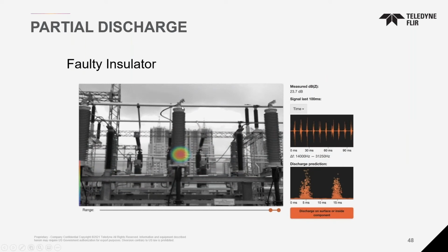We see this a lot, right? Why? Because insulators, whatever material they might be made of, are impacted by temperature, especially in our climates, there's cold and hot. This material will expand and contract, which eventually causes cracks. Those cracks allow water in, and it weakens the insulation properties. What happens is they start vibrating. Electricity starts vibrating this and that's creating ultrasound frequencies that we don't hear, but with the SI-124, we'll pick it up. And we can localize it.